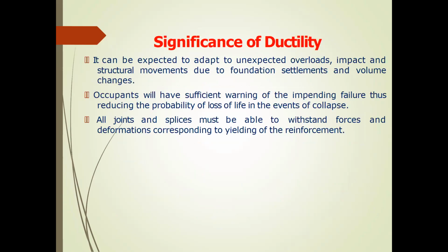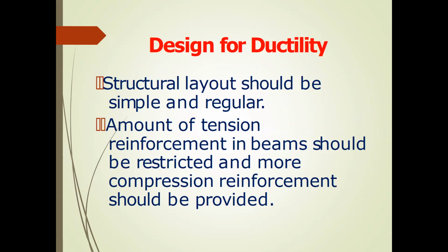Significance of ductility. It can adapt to unexpected overloads and impact on structural movements due to foundation settlements and volume changes. Occupants will have sufficient warning of the impending failure, thus reducing the probability of loss of life in the event of collapse. All joint splices should be able to withstand forces and deformations corresponding to the yielding of the reinforcement. Design for ductility.